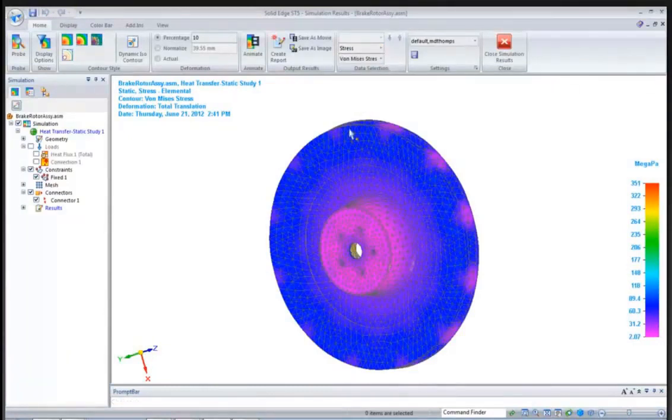So my stress values out in my area of concern here, again, we can't look at where we've constrained this. So that's, just to finish my thought, that's radiation. And you can look up emissivity and use that if you're going to consider radiation. So the results are back here. Stress is going to be high around my constraints. We know that. We ignore that. Out here, it's very low, as it should be, because we don't have the thermal growth constrained at all, really.